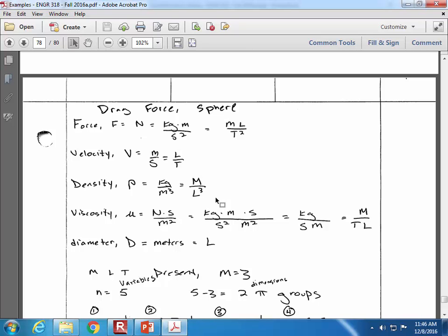And then also I want to have viscosity multiplied by diameter, and then I'll just have units of mass per time. And once I have started using one of these variables in combinations with other groups, then I cancel it out of the table. I'm not using it again. So the d exists in these remaining groups, but it's not continuing on its own. And the units of these groups are simpler than they were before.